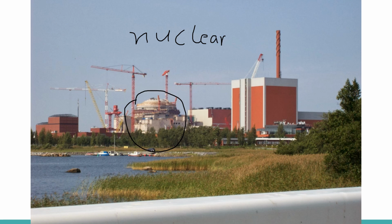In the case that the reactor gets demolished, you have a lot of hot water, and that water would evaporate, and to keep that hot water and all the other stuff in there, the radioactive material, you always build a big concrete containment. And this big concrete containment is one of the major costs. It's a 1.5 meter thick wall and a lot of steel in there to keep the steam in, just in case that there's something going wrong.